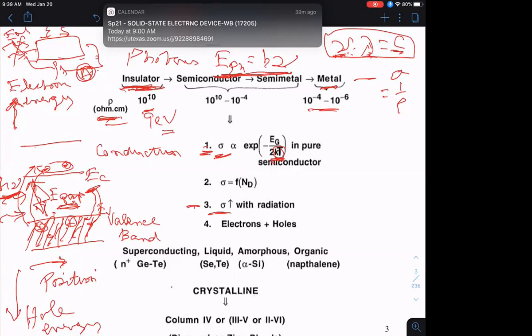And that's a very convenient measure of energy because, you'll be applying, I don't know, maybe 3.3 volts to a transistor, right? So immediately you know that the energy that the electron could gain would be 3.3 electron volts, all right? But sometimes you'll have to convert them to other MKS units, and the conversion would involve multiplying electron volts by the charge of the electron, which is 1.6 times 10 to the minus 19 coulombs, and that will give you energy in joules.